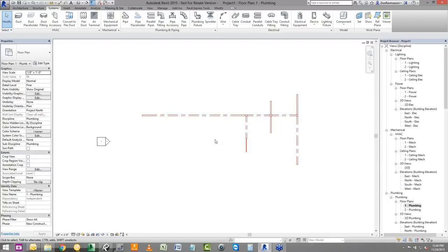We got a question about calculation and how many firms are using calculations inside of Revit. We have a lot of firms that we do business with that are calculating head pressure, they're calculating flow, but a lot of that is predicated on having all your pipes, types and systems all set up and ready to go. It's really hard. The analytics in Revit work really well, but they require you to have your setup done.